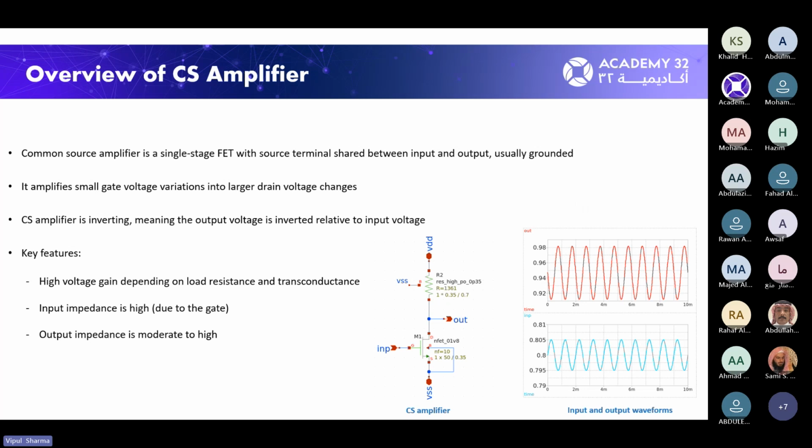Okay, so continuing with our overview. The schematic shown here is an actual circuit. Whatever symbols or nodes you are seeing, this is an actual circuit which has been designed and fabricated on our test chip, which we will be testing in the coming days. This is how you design a circuit inside an EDA tool. In our case, we are using an open source schematic editor tool called Xschem. This is how we represent it. So this is an amplifying stage, with the amplifying input transistor, an NMOS.